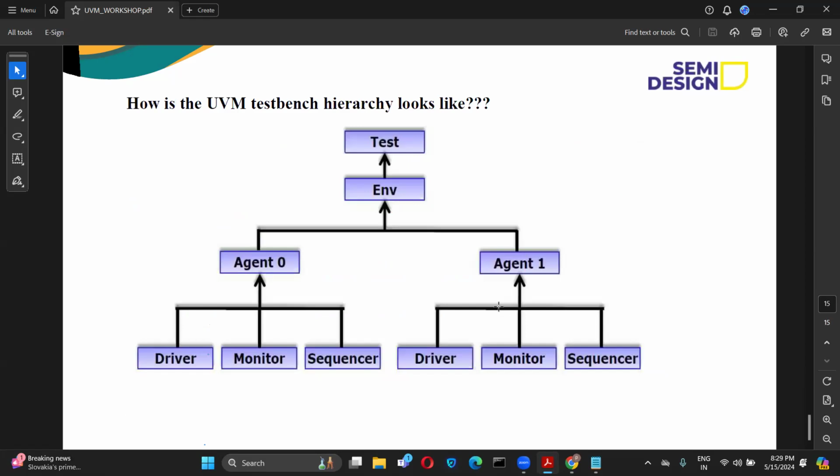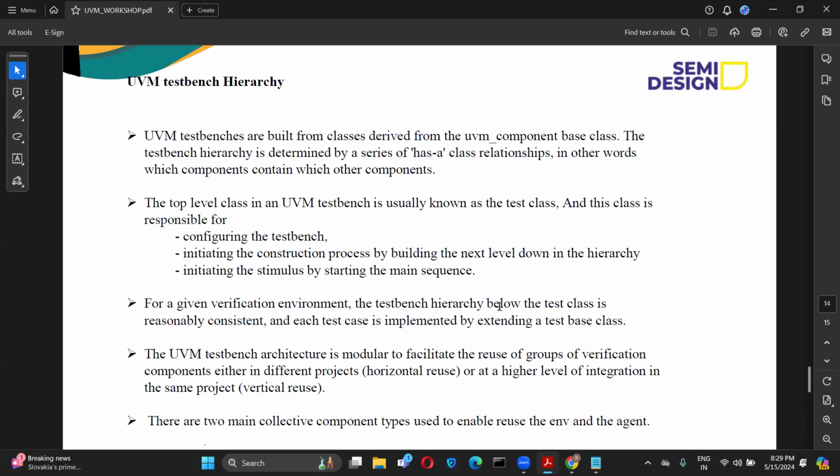Hello, ma'am. Can you go to the previous slide? Yes. I want to ask about this test class. Is this a class, or is it enclosed in module and endmodule? No, we are instantiating the DUT and doing the virtual interface setting for the config DB and run test. We do that inside the module and endmodule because that is a static component.